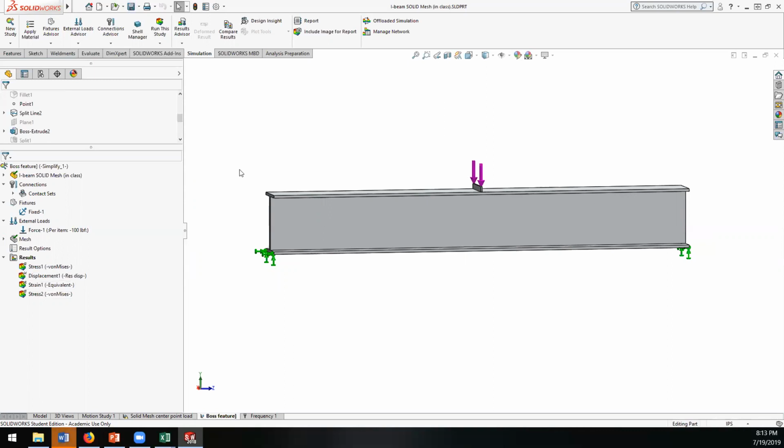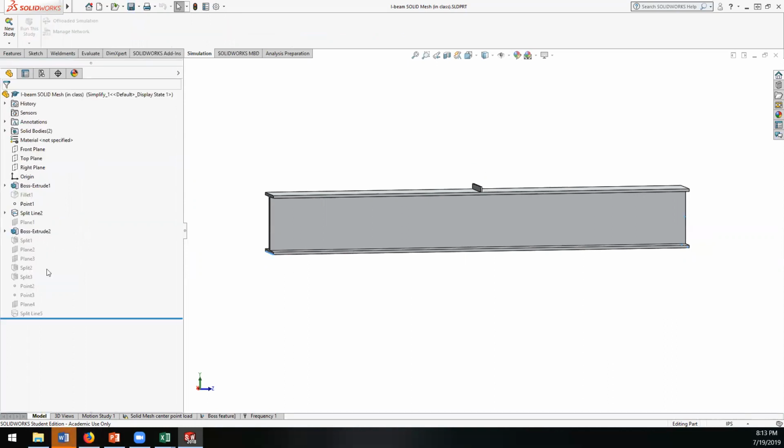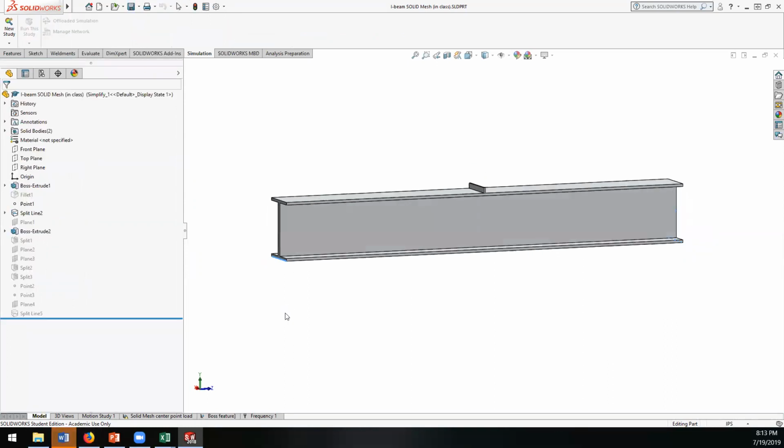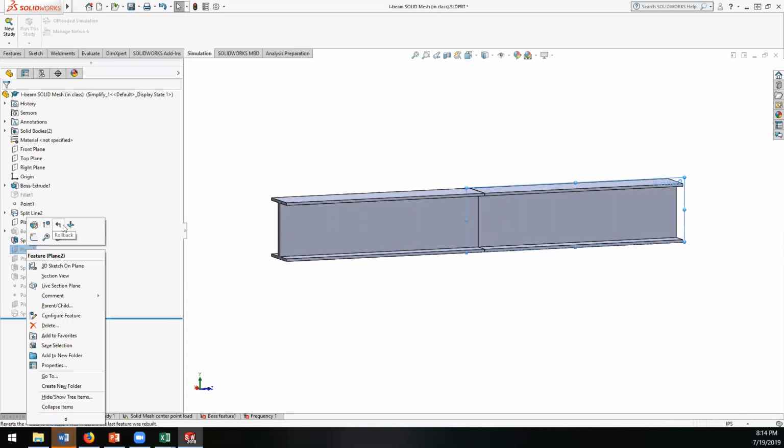Maybe I should just do a beam instead of the plates. Let me just show you the modeling for plates. I think I have it suppressed. So I'm not going to walk through analysis this way, but for the beam, there's also a way to do this where you split. So the other way to do this is to put a load on this entire face, on an internal face, right? So here I split the body. So I split this body in half. And then